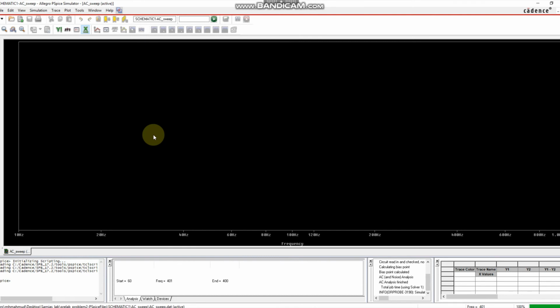So to get the impedance that you need to see in your pre-lab 1 problem 2, the impedance Z is the impedance that your voltage source is seeing in front of it. How do you get it? There is a hint in there. Just follow that hint, which is to plot the voltage of V1 divided by the current of R1 and use the absolute function. Absolute value is what you need, because Z is basically a complex number, so we just need to see the magnitude of it.